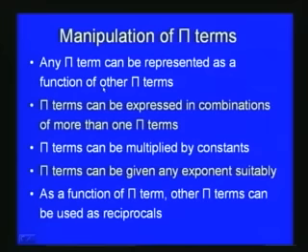So while doing dimensional analysis using the Buckingham pi theorem, the pi terms can be manipulated in different ways. We can represent one pi term with respect to other pi terms, or multiply by a constant, or reciprocals can be used, or we can suitably give exponents such that we get an appropriate dimensionless form, or the appropriate equations can be formed.